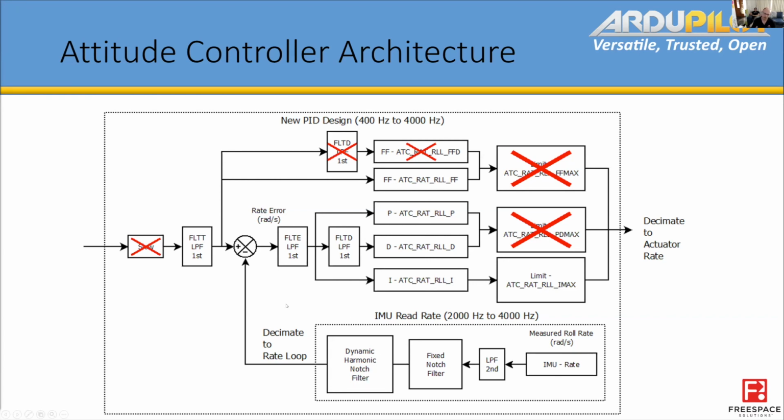And we still haven't got a real solid methodology for setting these, other than reaction time and the desire to preferably keep this at 10 and 20 hertz because the RC inputs are at about 50 hertz. So there's still probably a bit of gains to be had in precise tuning methodology and how we actually make full use of these things.